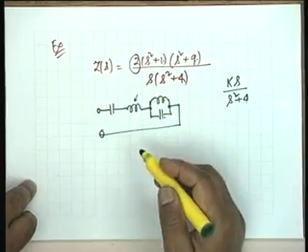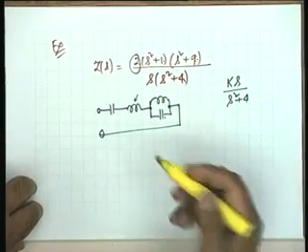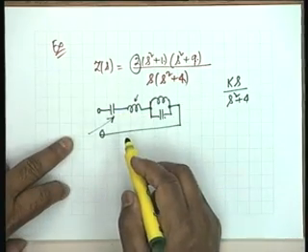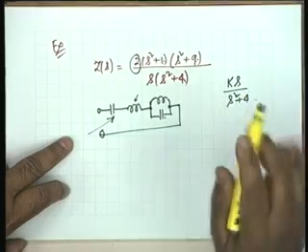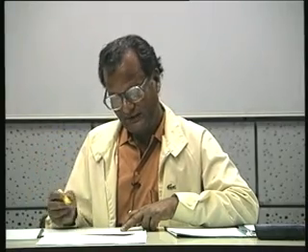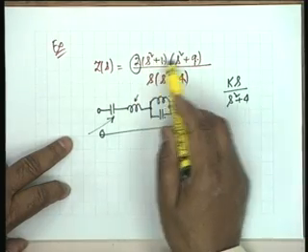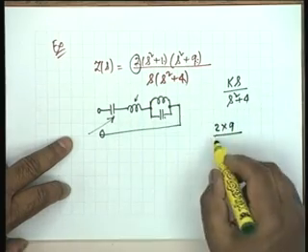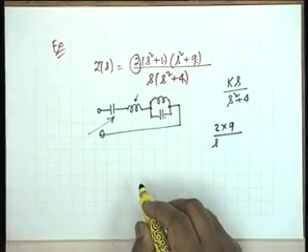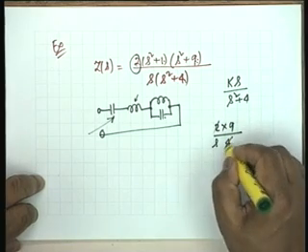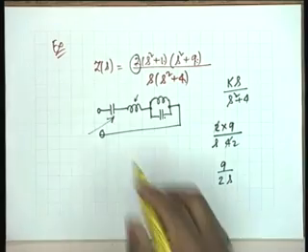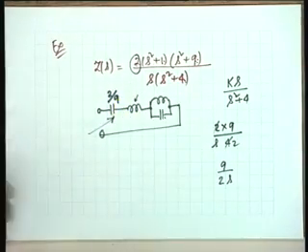Now to find the element values, can you also do that by inspection? This one, for example, the capacitor would be... The trick is you put S equal to 0. Then you get 2 into 1 into 9. So 2 into 9 divided by this S, keep this S because this accounts for the pole at the origin, 4. So it is 9 by 2S, 1 by SC.